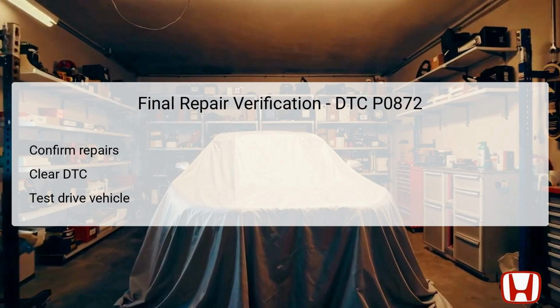It is essential to then test drive the vehicle under various driving conditions to ascertain that the transmission functions correctly and shifts smoothly through all gears. During the test drive, monitor the performance closely for any signs of the previous symptoms, particularly focusing on shifts from first to fourth gears. A successful resolution will be evident when the vehicle operates without returning to a fail-safe mode. This verification step ensures that the vehicle is not only repaired, but also safe for continued operation.